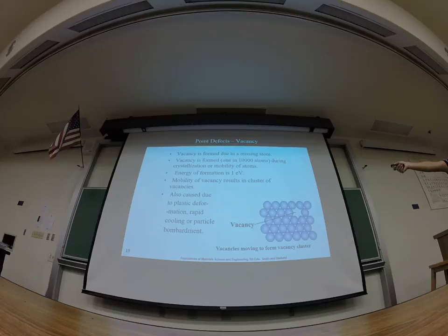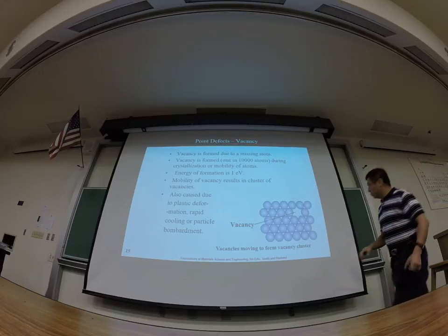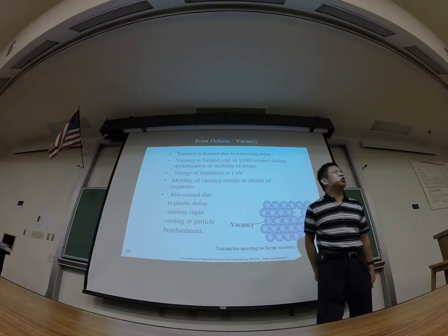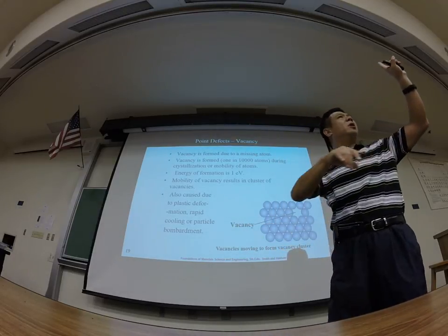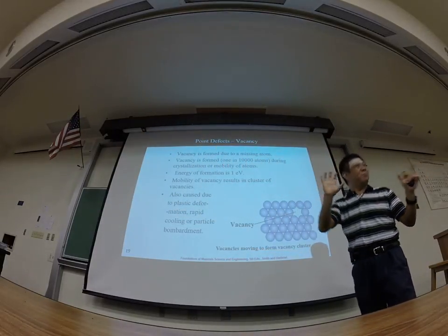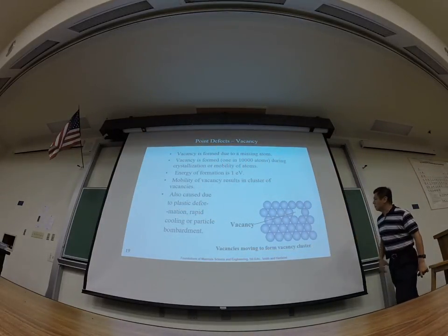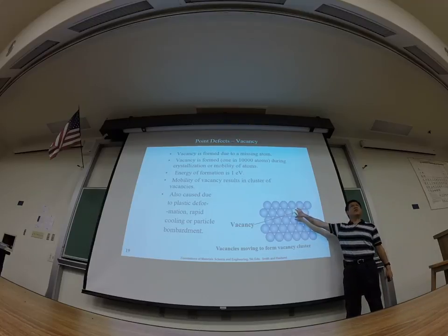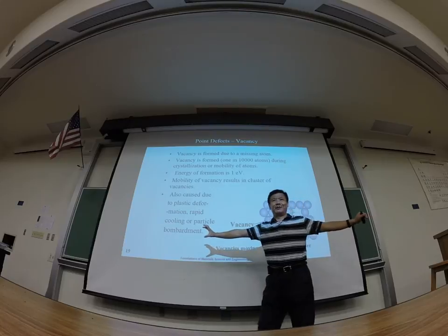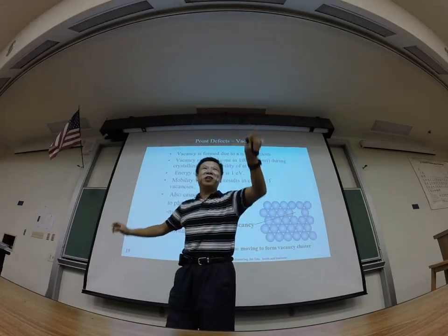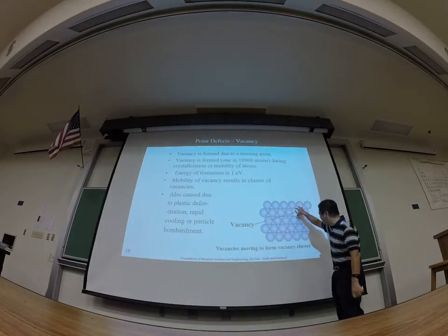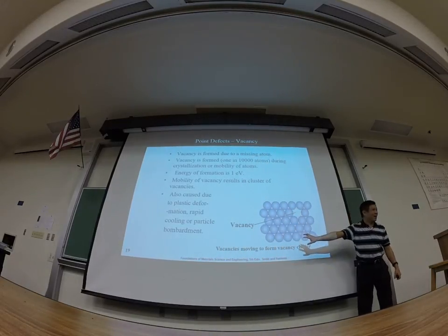Indeed, the vacancies, think about that one. The density of vacancies in some common metals is about 1 per 10,000, or could be larger than that, okay? But it's roughly in that range. That means it's frequent. Think about the three-dimensional packing of atoms. 1 out of 10,000 is not a small number. Okay, so that means you will frequently see the point vacancies.